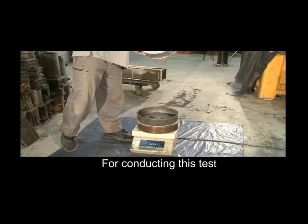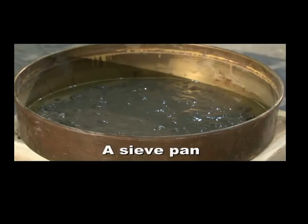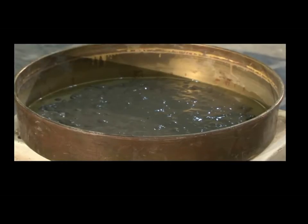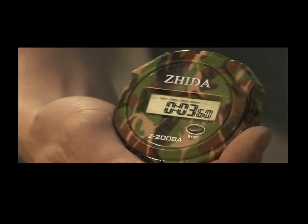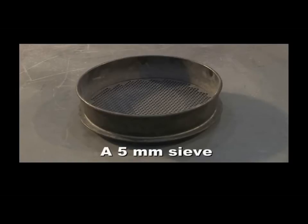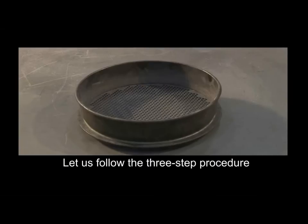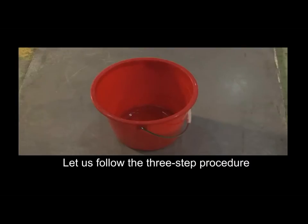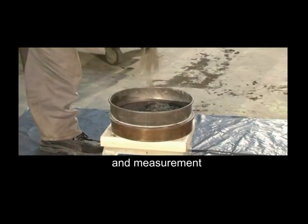For conducting this test, you will need a bucket with at least 10 litre volume, a sieve pan, a stopwatch, a 5 mm sieve, and a balance readable to 1 gram. Let us follow the 3-step procedures: preparation, casting, and measurement.